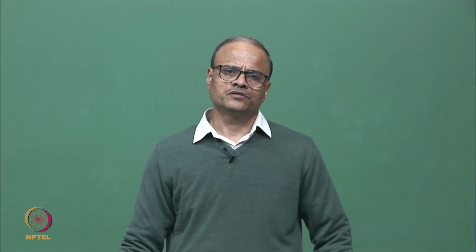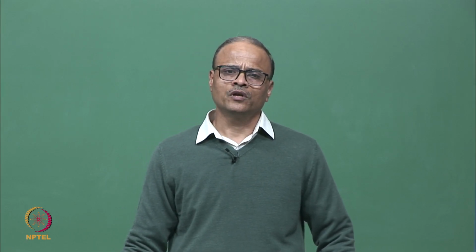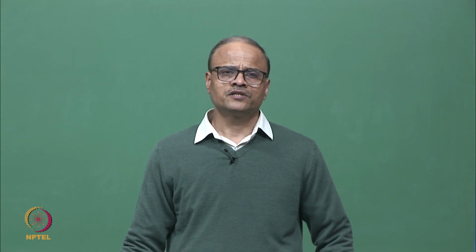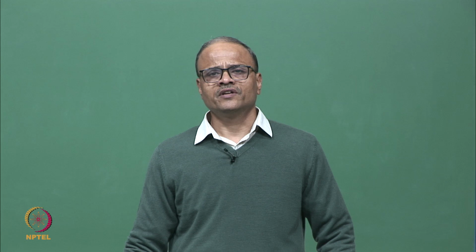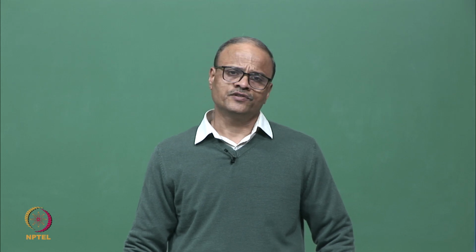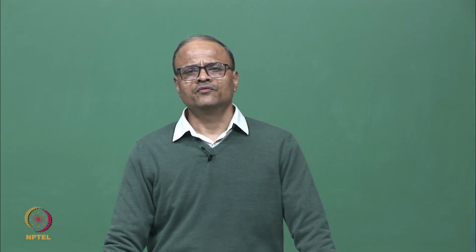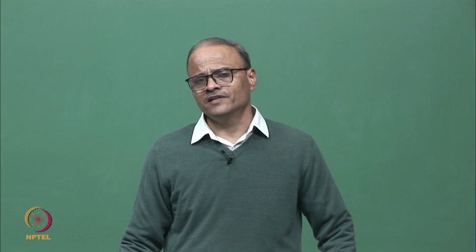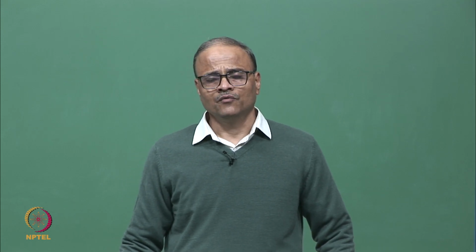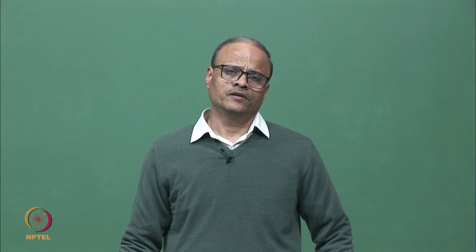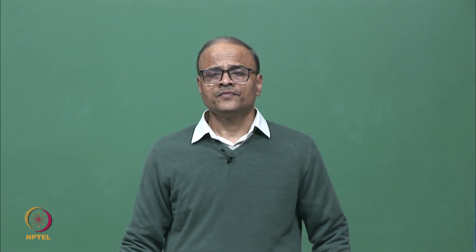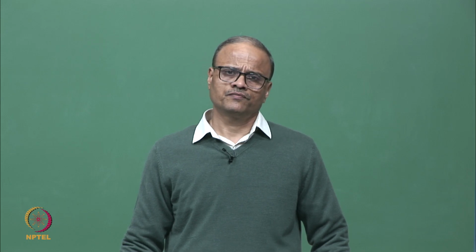In the previous lectures, we have studied vibration and modal analysis of single and multi-degree of freedom systems. We also studied the concept of frequency response function, which characterizes a system in the frequency domain. In this lecture today, we are going to talk about impulse response function, which basically characterizes a system in the time domain. We will also talk about how to find the response of a system to a given transient force or a set of forces using impulse response function.